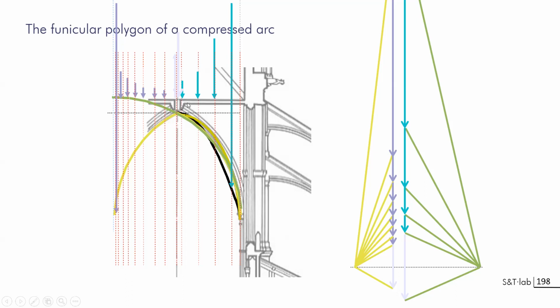You can see if you divide just the applied force at equal distance, we need more and more important forces on both sides on the right. And if this is the load, so this is a case of an arch, for instance, and in the case of vaulting, you will have to distribute forces all along the arch, and you see that these loadings are growing when you are going on the side. And actually, again, you will have the difficulties when your line is getting vertical on both sides, so you have to interrupt it just before, and using, for instance, flying buttress to create these forces.